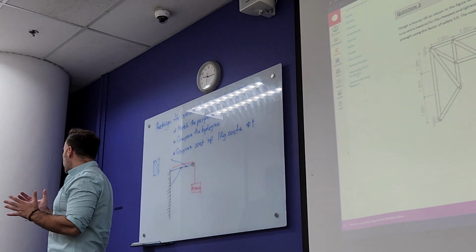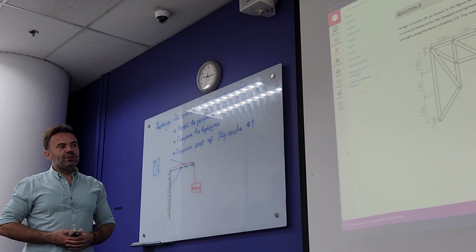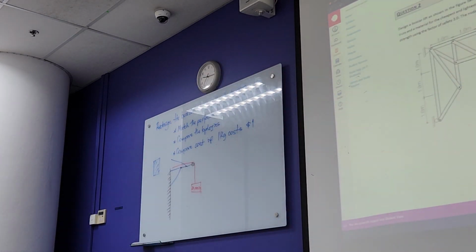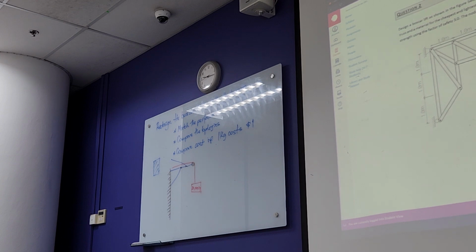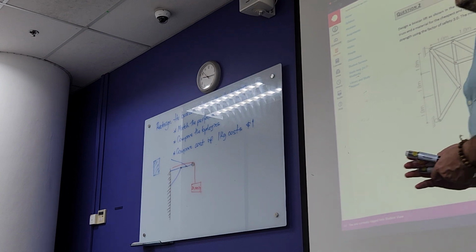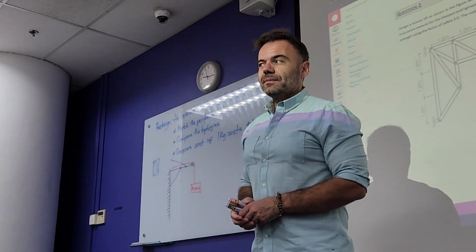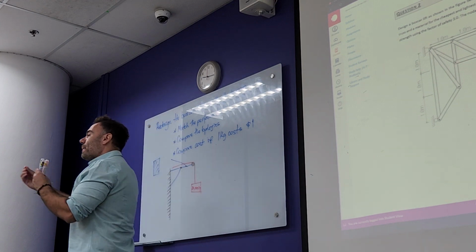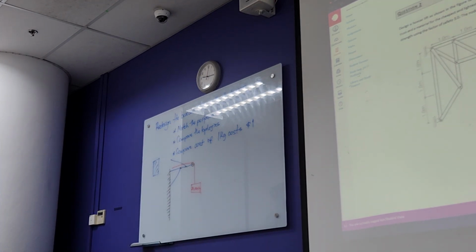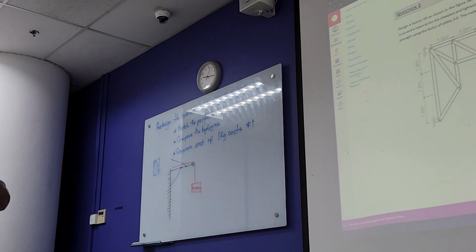What commonly could happen, and happens all the time, is when it comes to structures like this, we've got students putting nodes there and there. And the structure all of a sudden looks like that, becomes wiggly, like that. And they said the structure failed. The structure did not fail, it was you who failed, who didn't model that right. Yeah? So be mindful of those things. So that is the decision that you have to make. What is the appropriate element size?